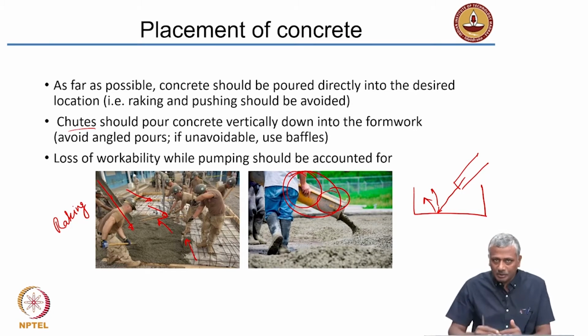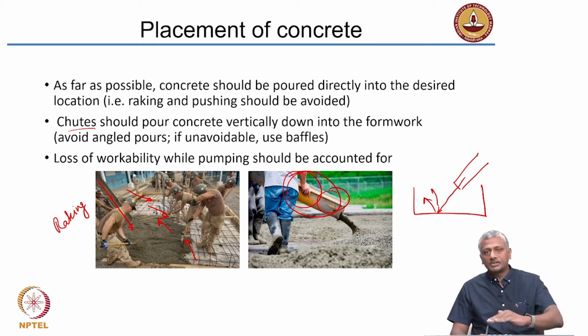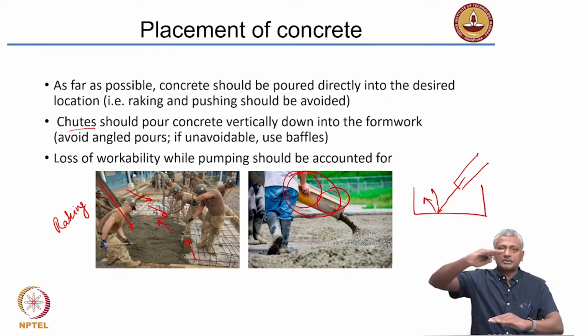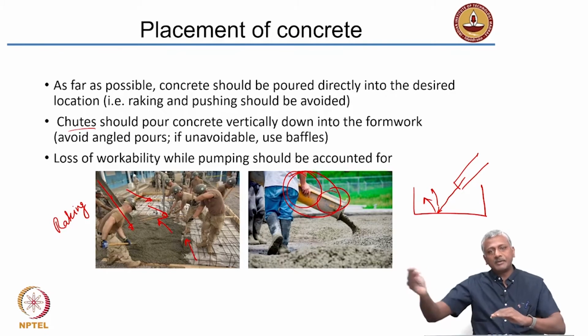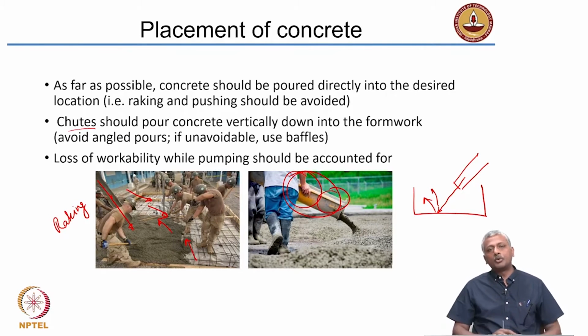So you need to design the concrete at the ground floor for sufficient workability, so that any losses because of the pipe travel can still be compensated at the time of the pouring.